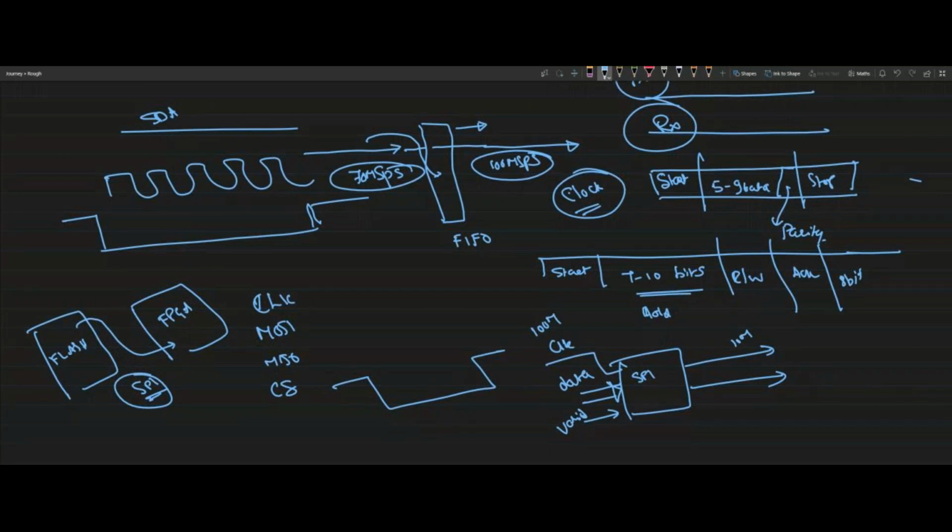Suppose I'm writing some code that I need to run in the FPGA. For that I also need a protocol, right? I will connect all my signals to that interface. No, it depends on what code you write, what code you are actually planning to write. So not all code needs an interface. For example, if you are internally computing something through LUTs or some computation, and you don't want to communicate with an external IC, then you need no interfaces. If you have a requirement for external ICs, then only is the interface required.